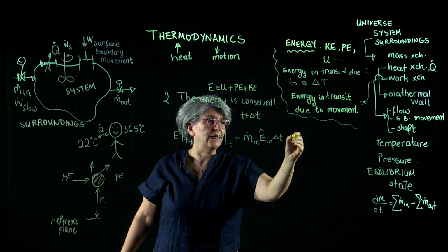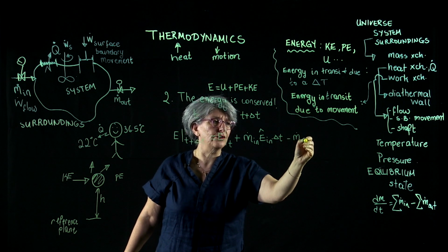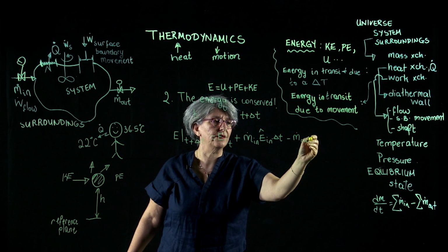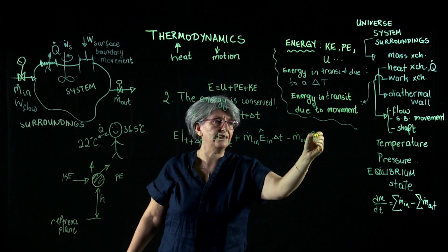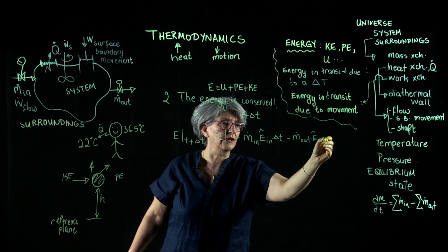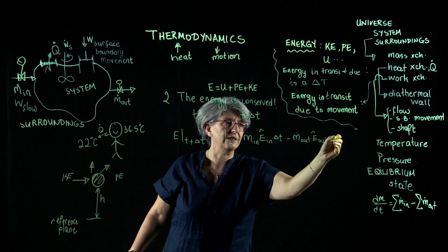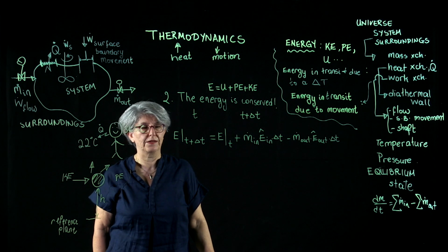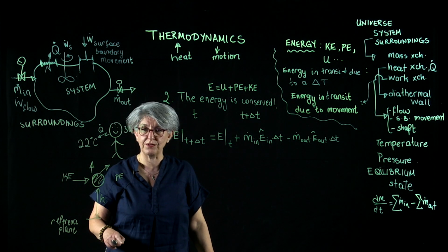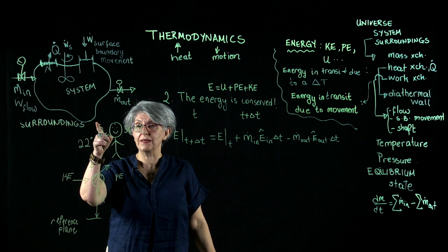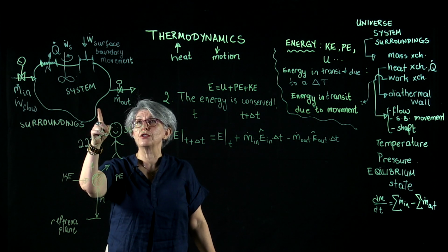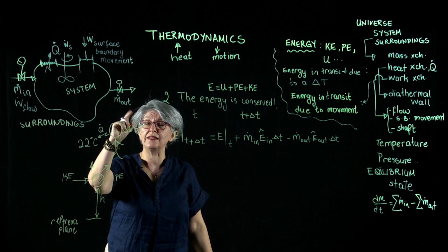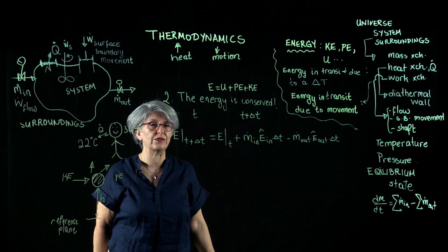Minus m dot out times E hat out times delta T, and we are not finished. We have to take heat, shaft work, surface boundary work, and the flow work into consideration.